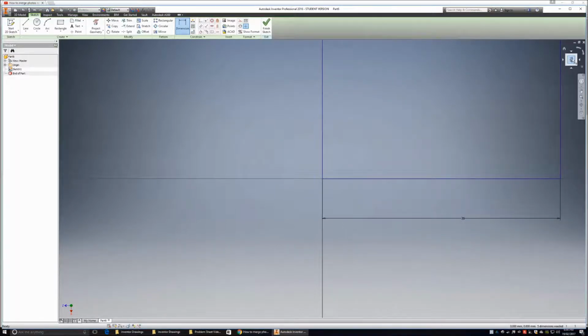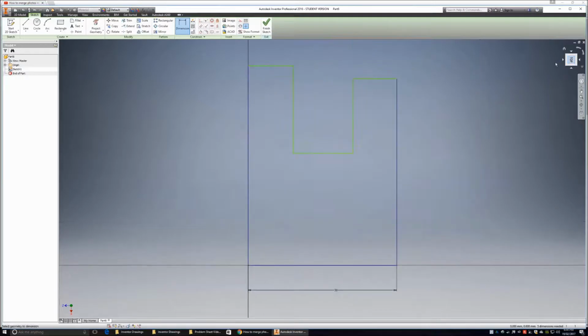Going to go back up to the top, to my top here, so I can see my whole image, because I want to now do from the top to the bottom, because I've got that dimension which on my drawing tells me it is 20. So 20, enter. I'm going to do the same on the other side, click and click. Now I have a couple of options here, and I'm going to use the first option, which is just put in the same size, 20, enter.